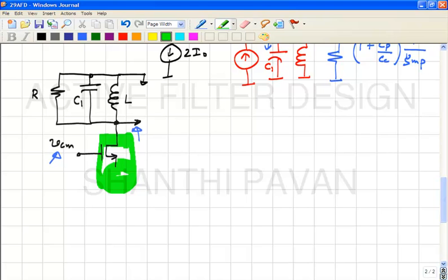This is exactly the same as the differential pair argument, right? In a differential pair with a tail current source, if the common mode changes, what do you think will happen to the output common mode? It doesn't change because of the common mode rejection ratio of the differential pair. Okay, so please note that you must all be very, very thorough with the differential pair, right? It's perhaps the most important circuit. It's governing all our lives because everything in the world is a differential pair, right?